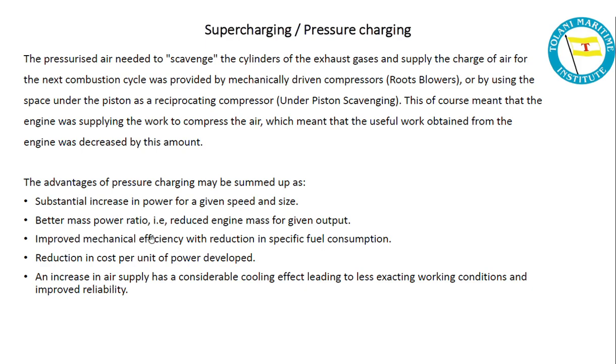Better mass power ratio, that is reduced engine mass for given output. Improved mechanical efficiency with reduction in specific fuel consumption, SFOC decreases. Reduction in cost per unit of power developed. An increase in air supply has a considerable cooling effect, leading to less exacting working conditions and improved reliability.